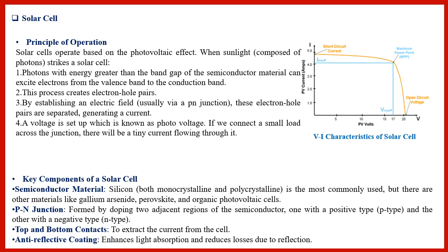When a very thin layer of p-type semiconductor is grown on a relatively thicker n layer, a fine electrode is placed over the p-type layer. The layer is such that it doesn't obstruct the light, that I already discussed in the previous slide. A current collecting electrode is provided at the bottom of the n layer, and further we just encapsulate it in a thin glass to protect the solar cell from the mechanical shock.